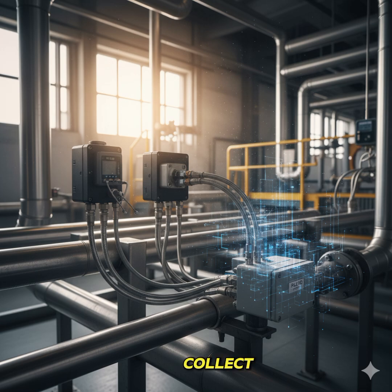SCADA systems collect real-time data from sensors, transmitters, and field instruments installed at remote sites. These devices send their data to PLCs, programmable logic controllers, or RTUs, remote terminal units. The PLCs and RTUs then communicate that information to a central control system, often called the SCADA server.